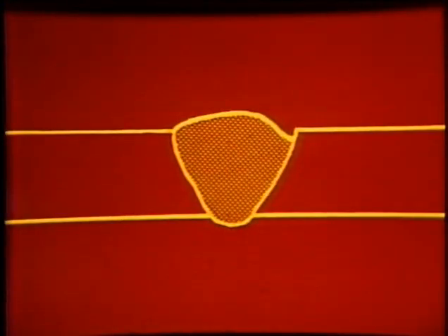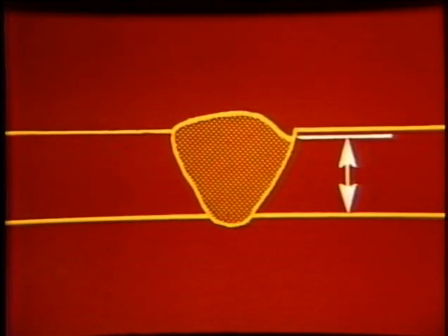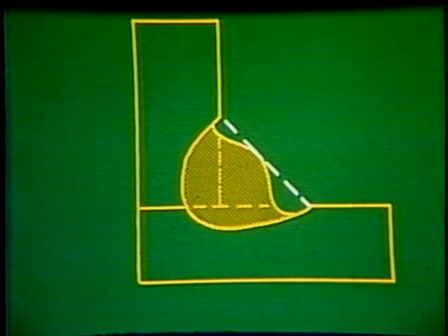It is also commonly present at the toe of the last or cover pass of a welded joint, resulting in a reduction of base metal thickness at the point of undercut. In fillet welds, undercut tends to reduce the size and strength of the weld, as well as promoting stress concentrations at the toes.